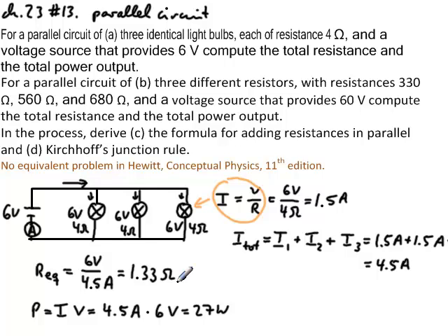So we have 4 ohms, and we add 4 ohms and another 4 ohms, and the total resistance is supposed to decrease below 4 ohms, of course. Apparently it is 1.33 right now. Overall resistance lowered with each added path between any 2 points of the circuit. This means the overall resistance of the circuit is less than the resistance of any of the branches, and that's